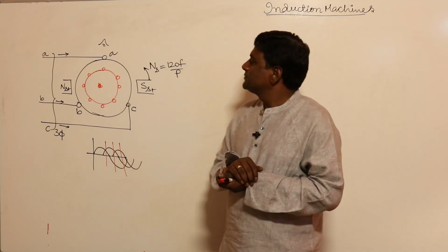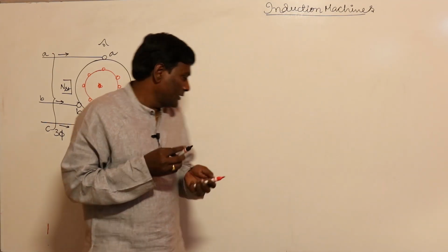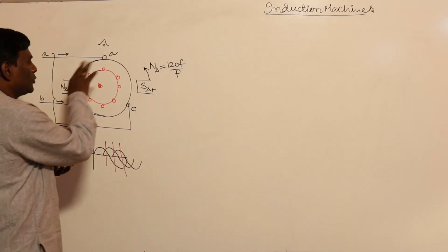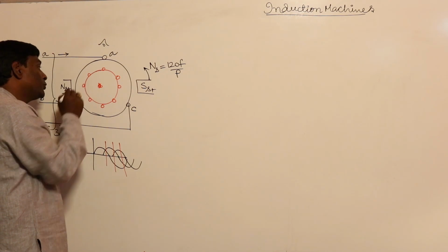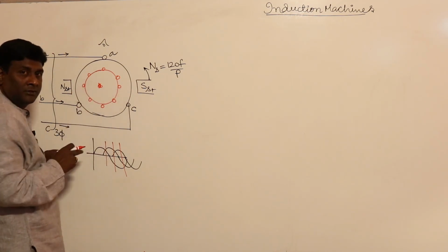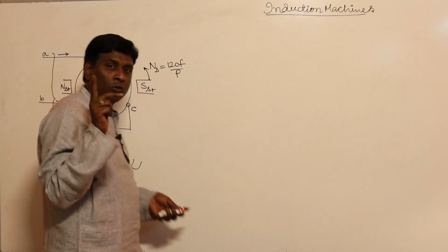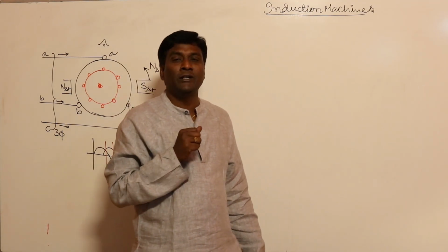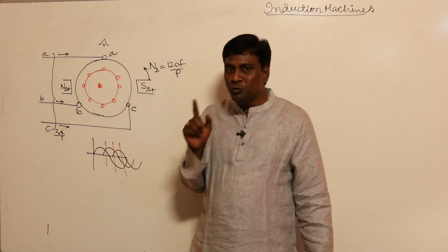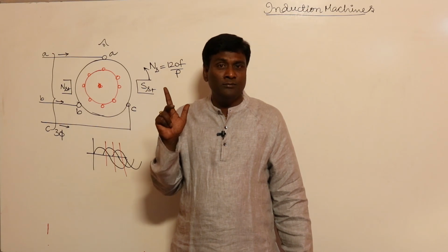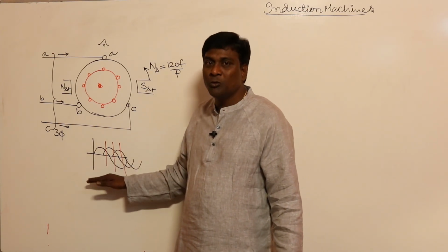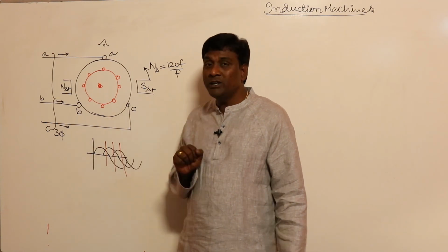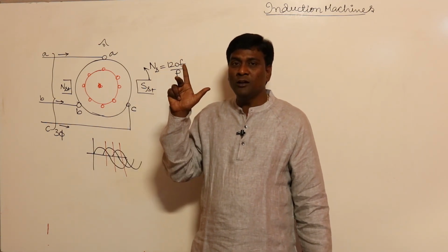Now see here, voltages are going to be induced, and here is where you are going to get maximum induced voltage in these conductors. Now let us apply the right hand rule, for induced voltage. It may be motor or generator. Yes, it is a motor. We are discussing the motor, but still for induced voltage we have to apply the right hand rule.